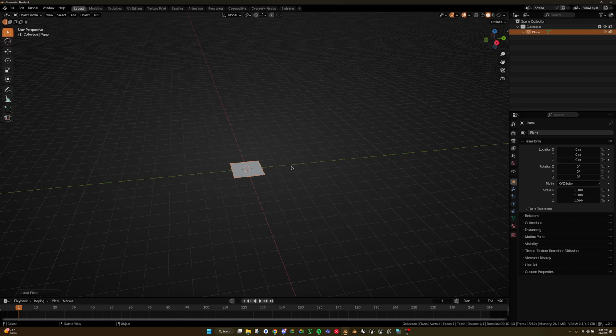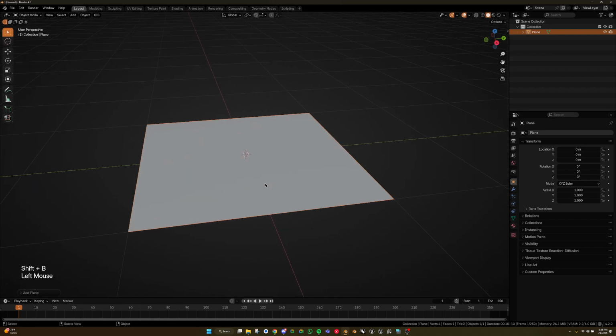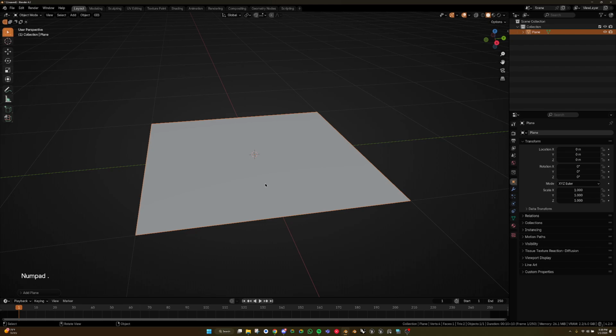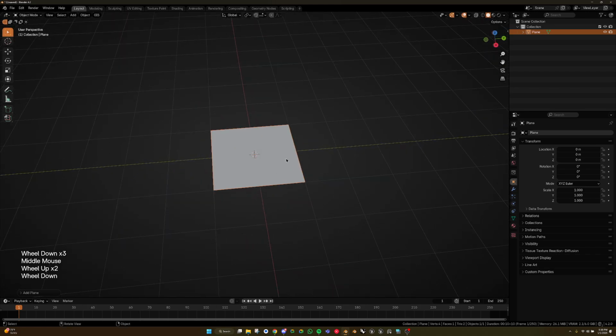and I'm going to zoom to selected by hitting Shift B, or I can press the period on the number pad, or I can hit the squiggly underneath the escape key. I call it a squiggly. And then you click view selected once you have it selected. This is how you focus your view on what you're working on.